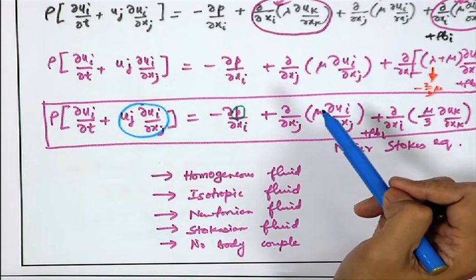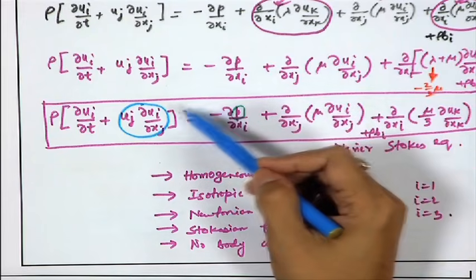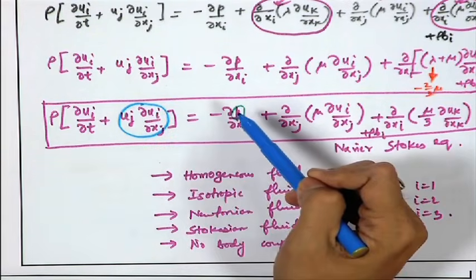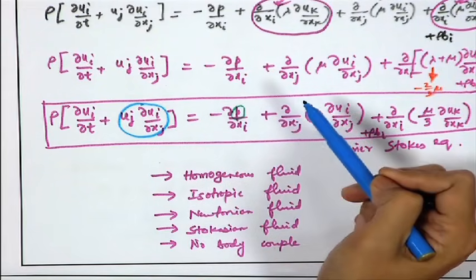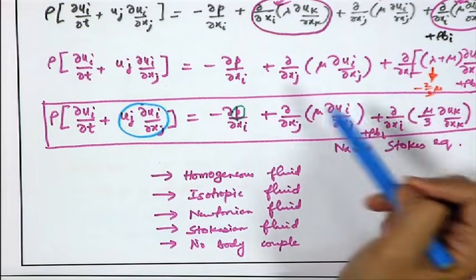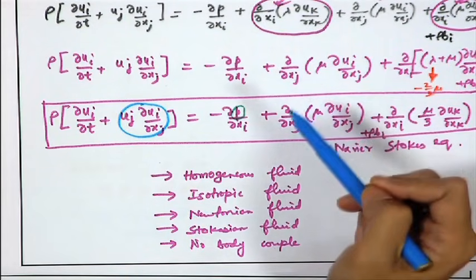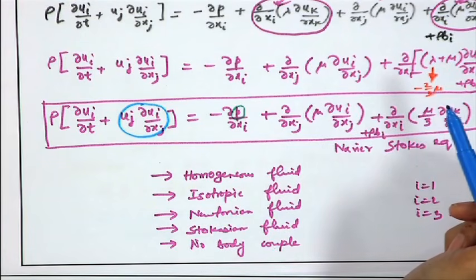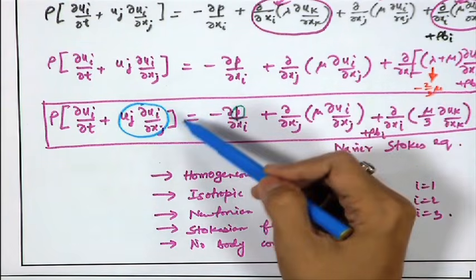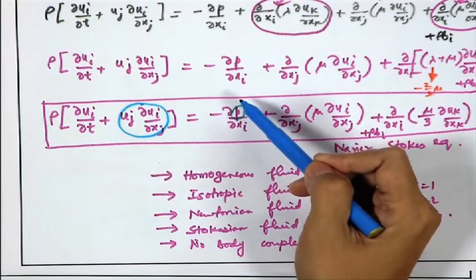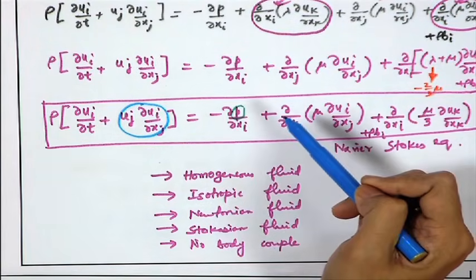Then Stokes equation is the Navier-Stokes equation with this left hand side equal to 0, and Stokes hypothesis that we have discussed today, that is lambda is equal to minus 2/3 mu. So you need not confuse all these Stokes law, Stokes equation and Stokes hypothesis. And so until and unless the left hand side is 0, it is a system of coupled nonlinear partial differential equations.